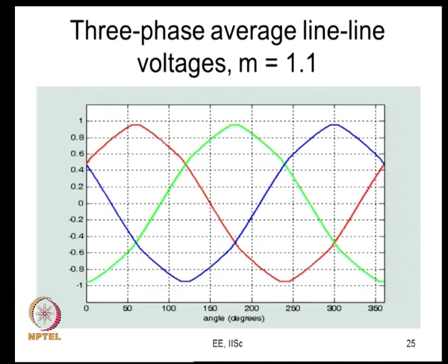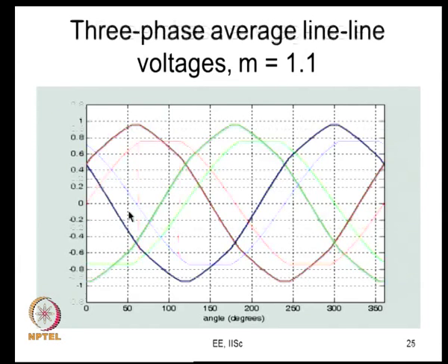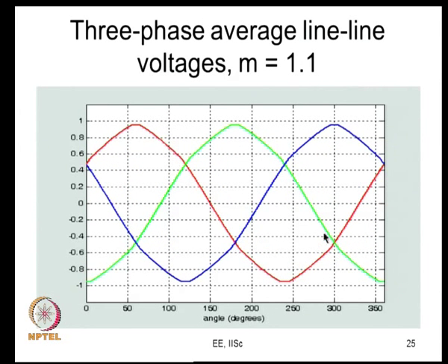Now, the procedure is clear, I have already delineated the procedure. So, when I subtract that, what happens now? Now, you look at these, they are sinusoidal voltages now. So, what has happened between the earlier thing and now? Whatever the harmonic components were, the triplen ones have got knocked off, they have been removed, and all the other components like 1st, 5th, 7th, 11th, 13th etc. get multiplied by a factor root 3 and they are here. If you do a harmonic analysis of this, you will find fundamental, 5th, 7th, 11th, 13th etc., and these harmonic amplitudes will be root 3 times the corresponding amplitudes for VRO average etc.